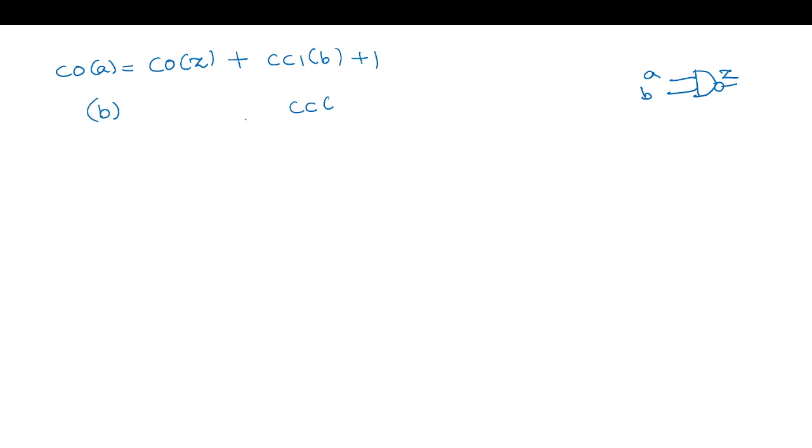So now for the NAND gate, A, B, Z, we have discussed, right, till now. For the NAND gate, to observe A here, it is this node's observability plus the non-controlling value, which is 1 for this. Now if we go for B, this should be non-controlling A plus 1.